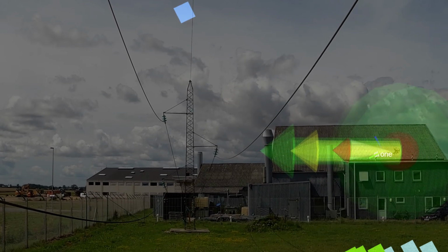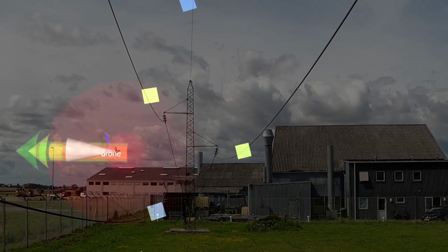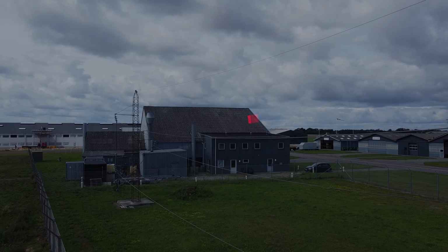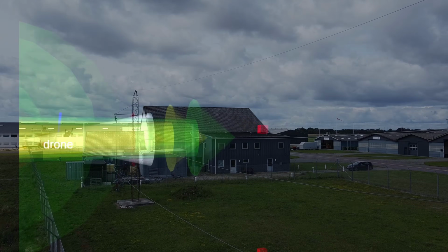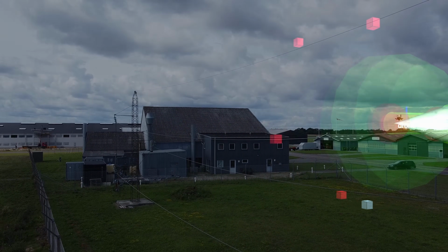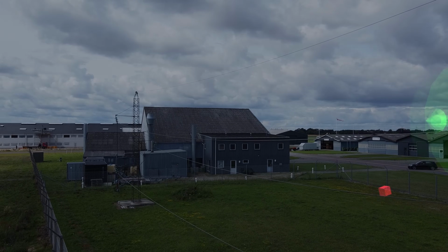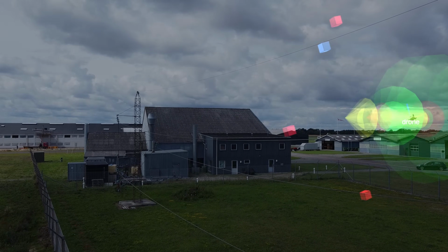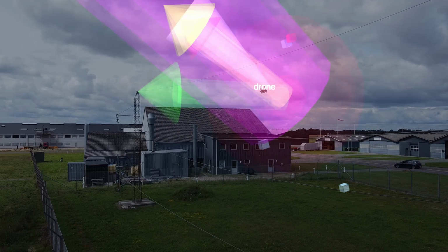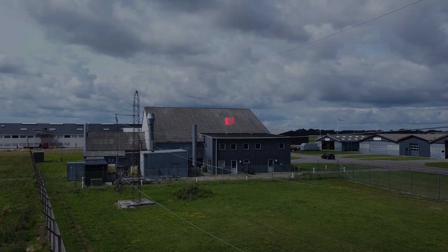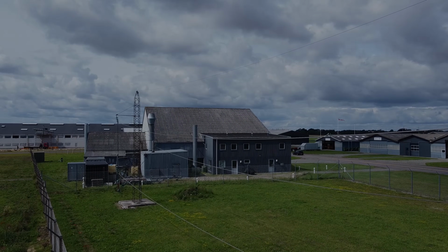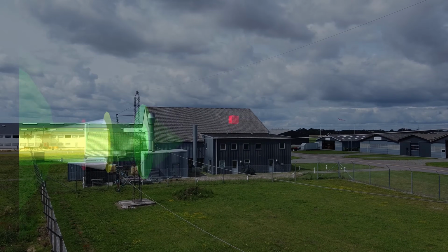At higher speeds, an e-brake horizon, visualized by a gray cone, extends from the UAV in the direction of travel. If a detection is made inside it, the drone immediately reduces its speed. Once below a safe threshold, normal power line avoidance resumes. The maximum length of the e-brake horizon, and therefore also the maximum allowed speed, depends on the direction of travel. Since the front sensor has a longer range, higher speeds are allowed in this direction.